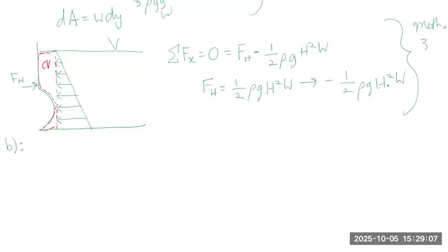So basically, for part B, we know that the vertical force on a curved surface can be represented by the weight of the volume of water above that surface. This will come in useful later. But first, let's analyze what the forces are on our chosen segment of control volume. Our semicircle structure looks like this. Let's call this point E. Let's call this point A.